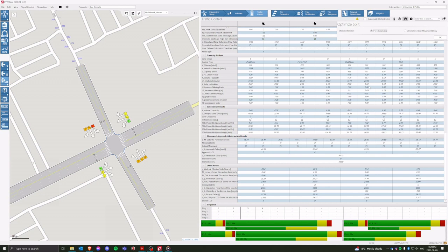And those are based on performance measures. So things like level of service, volume to capacity ratio, or queue length. And so very commonly you'll see something along the lines of, if the movement is performing at level of service E or worse, so in other words E or F, then further remedial measures are required.